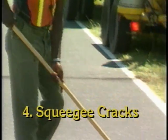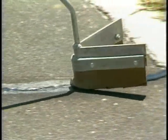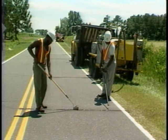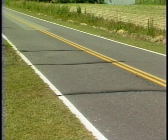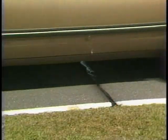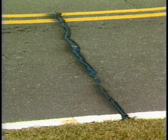Squeegeeing of the cracks is the 4th step in this procedure. Use a hand-held squeegee to smooth out any excess sealant after application by the sealant wand. The squeegee follows immediately behind the application wand because the rubberized asphalt cools quickly. Once the sealant has cooled, the roadway is open to traffic. No blotting is required with rubberized asphalt. Using these operating procedures will result in effective crack sealing and will protect the pavement and retard future deterioration.